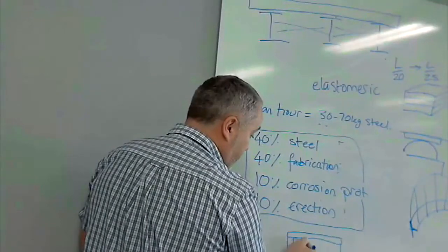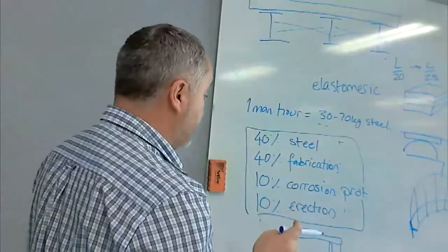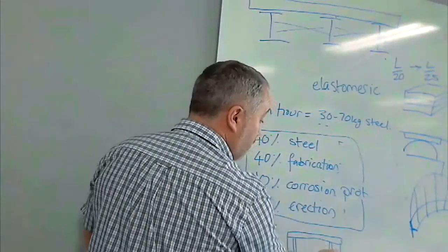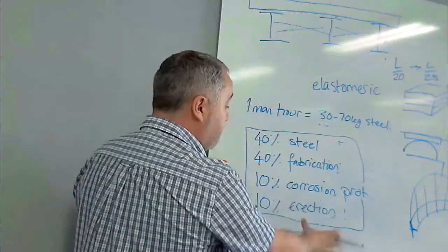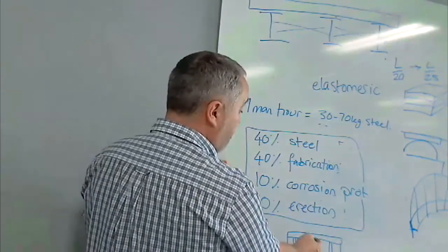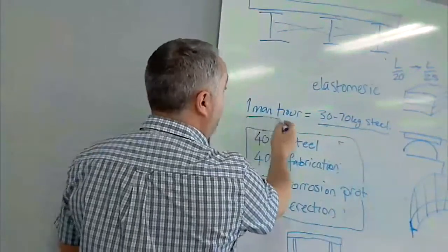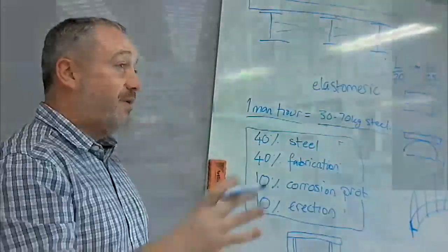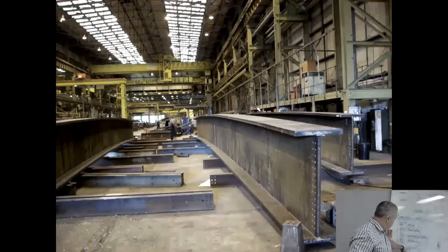They might put some stiffeners in to improve the shear, and all of these options are just weighing up the amount of steel compared to how long it would take someone to fabricate it. They're trying to reduce the cost of the bridge, because each stiffener can take like three quarters of an hour to put in.